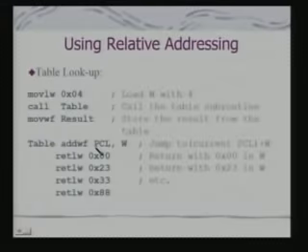If you see here, the current content of W will be added to PCL, and it will jump to the current PCL plus W. So, the moment this offset is added, the current location is this PCL plus W, and this has been done through an arithmetic operation. We have not executed any branch instruction at all. This is very, very interesting. We have not executed any GOTO or conditional branch, we have just done an addition operation.